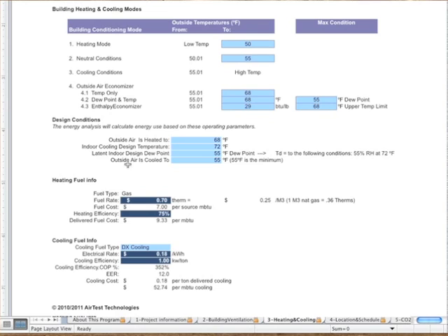And then when outside air is brought in, really to be cooled down, it moves through a cooling coil, which in this case we're assuming is 55 degrees. And of course, when you cool it to 55 degrees, you bring the dew point to 55 degrees. So that's why those two are equal. And generally, if you're adjusting this number, you should try and make them equal.